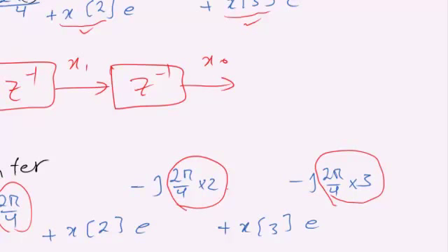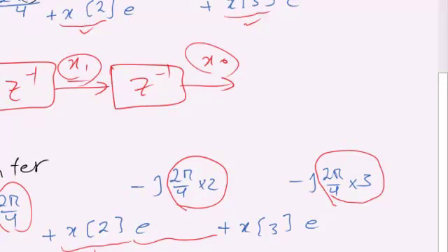It is going to be used to calculate this part, and then you need just a multiplier to multiply the different instances that you have here, here, and here by the exponential block, and then you need an adder to do the additions. So in this case, all coefficients of DFT could be calculated, and then you can simply implement it on a DSP board.